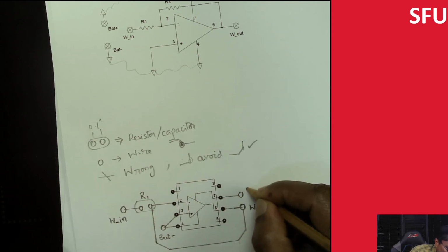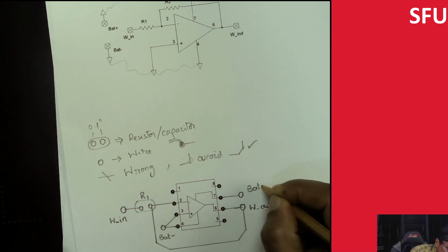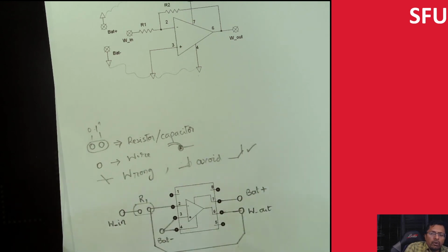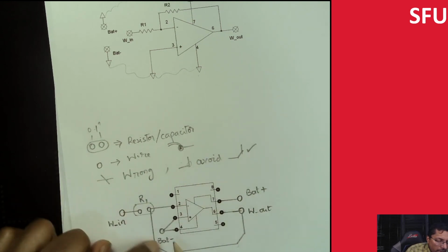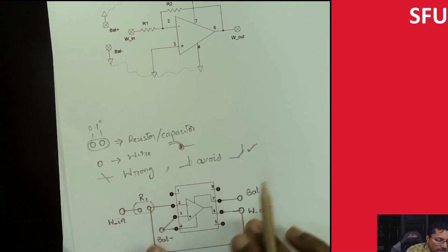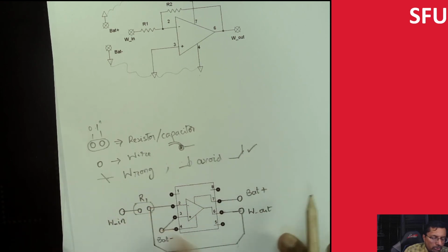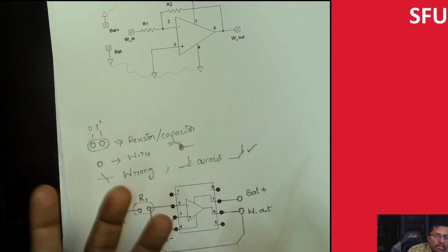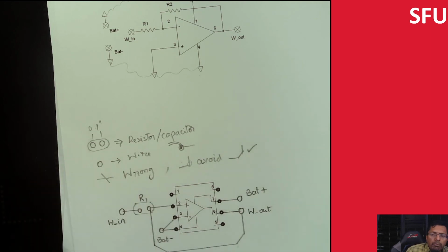All this battery plus. So if you're connecting an actual battery, you might need to do something more clever. What you could have done is have this go underneath the circuit, so then there's no crossing, and then you can get both of this battery and put a battery block over here that is going to power the circuit. So this is the simple layout.